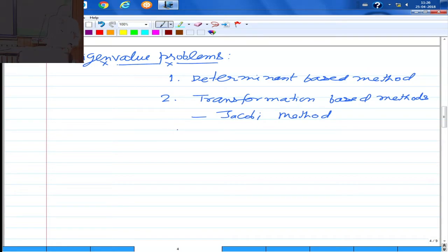So we have this eigenvalue problem, omega n square M into dn is equal to K into dn. So this is our general eigenvalue problem, and in general K and M both have non-zero off diagonal elements. Of course, if M is used as a lumped mass matrix, then all the off diagonal terms would be 0. Otherwise, in general, they have non-zero off diagonal elements.